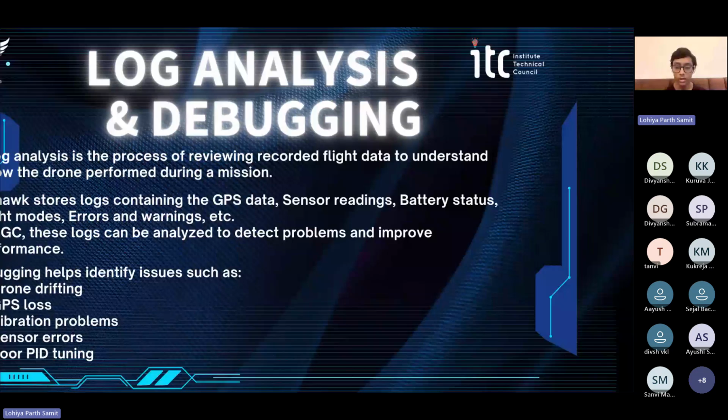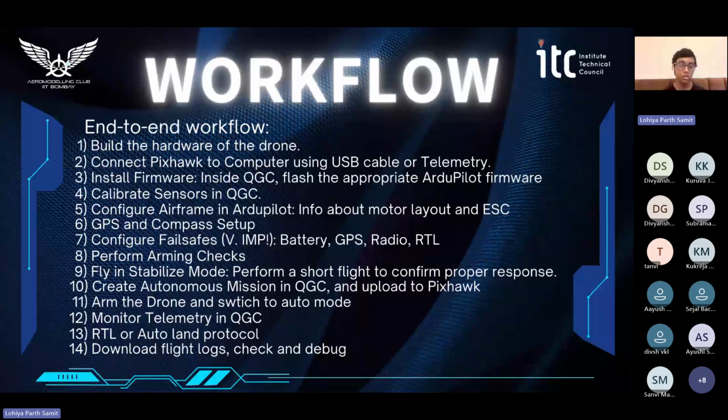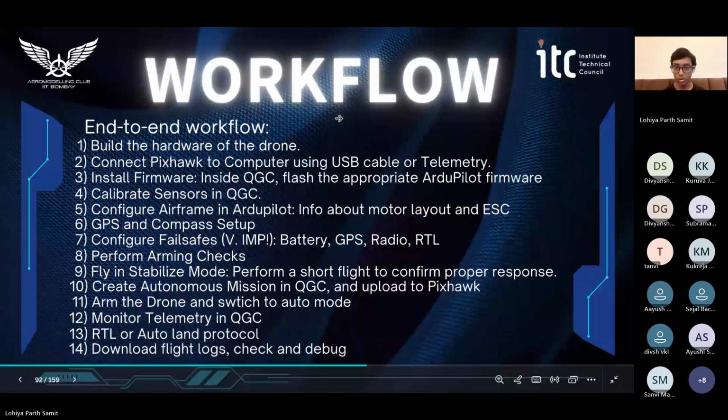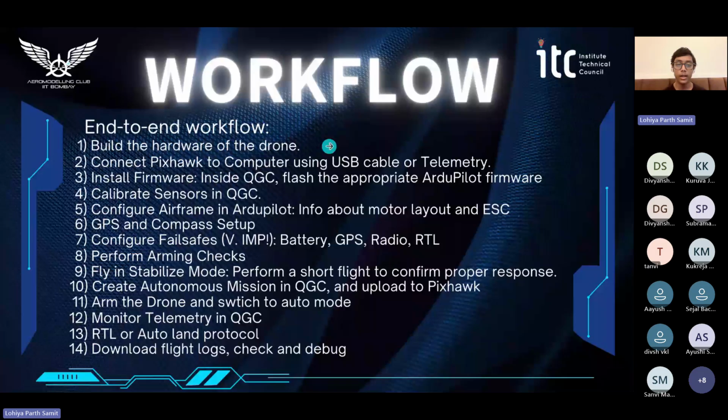Now we'll move towards the end of my session. So the entire workflow that can help you to design a drone from scratch. So this is the first step. That is, we build the hardware of the drone, the body of the drone that is. Then we connect the Pixhawk to the computer using USB cable or telemetry. Then we install the firmware, that is the program inside QGC. We flash the appropriate ArduPilot firmware.